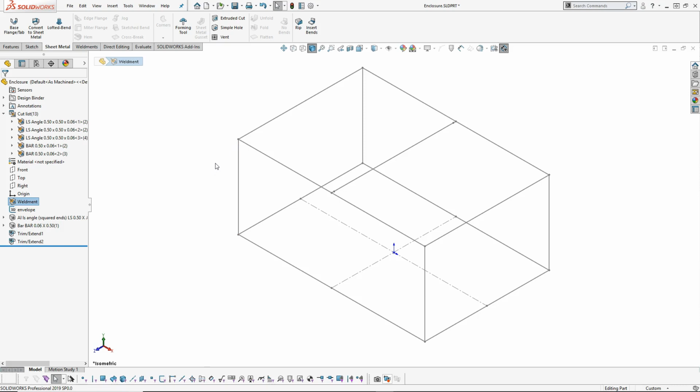I'm not overly concerned with maybe a little bit of a gap, or depending on the variation in the materials, a little bit of a reveal along those edges. My intent to seal this up is to put a bead of silicone, and then when we tighten everything down, just pretty much let that be the gasket seal.